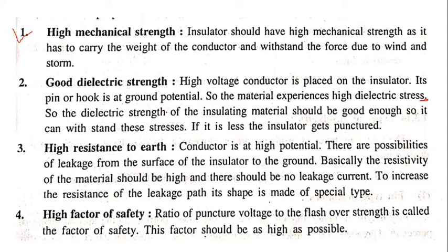So the dielectric strength of the insulating material should be good enough so it can withstand this stress, so that flashover may not occur in this situation. That's why we require a good dielectric strength for our insulators. If it is less, the insulator gets punctured. Whenever the dielectric strength decreases, at that time the insulator is going to be punctured.